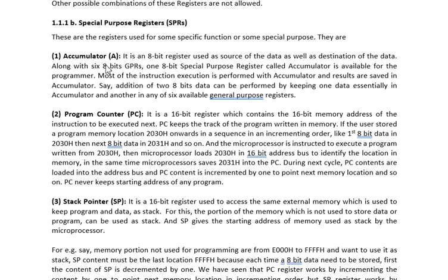The microprocessor will perform this addition with the accumulator as one operand, and it can take any general purpose register as the other: A plus B, where B is a general purpose register and A is the accumulator. Accumulator plus C, accumulator plus D, accumulator plus H, accumulator plus L, any register. You can also add accumulator plus accumulator.